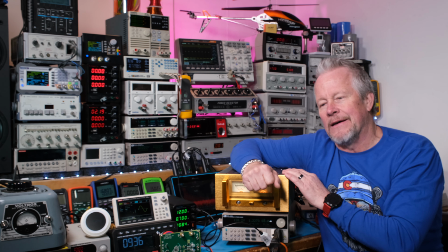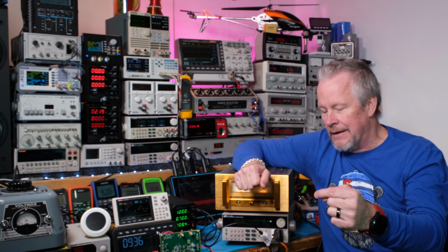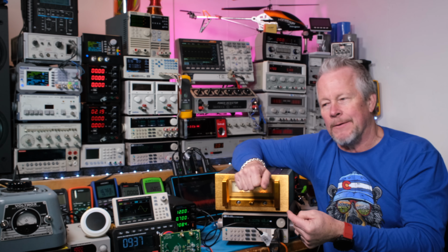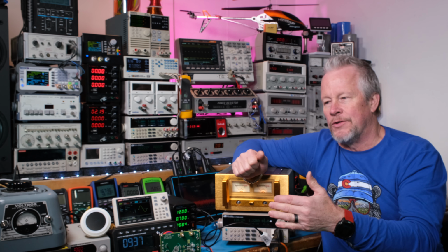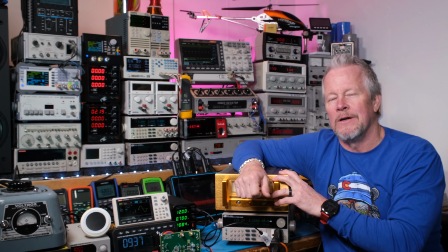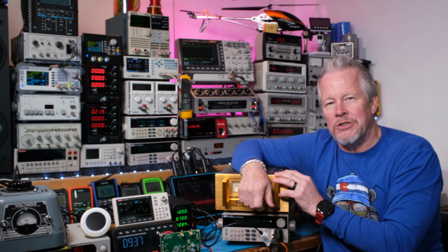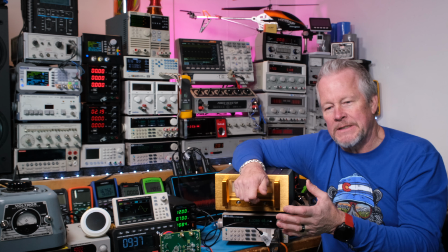And then we can line up the current and the voltage and keep the power factor near 1. So the VA and the watts going in are essentially the same thing. You don't need, say, 130 VA to give 100 watts. You don't have to have that extra overhead on your power system. You're actually using what you're asking for. So the first stage is that.